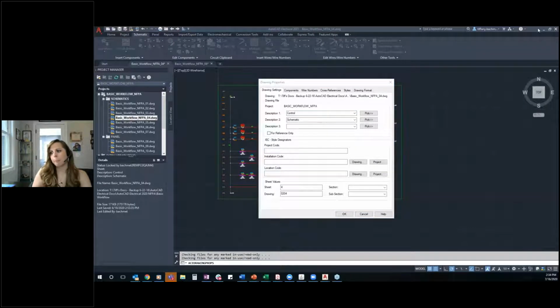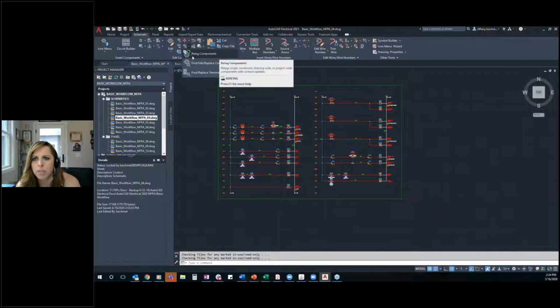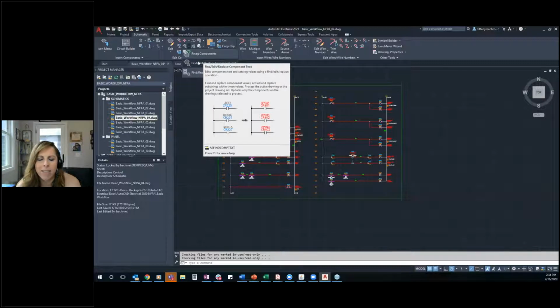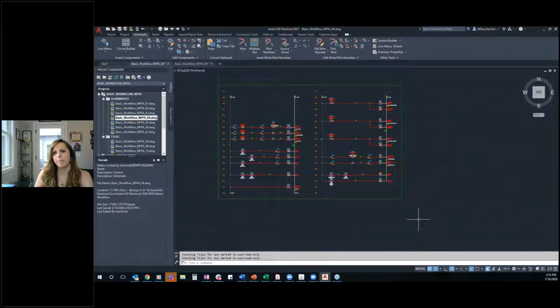And then Tiffany, I think you use the Find, Edit, Replace tool on the project tab. Ron is asking where that's located. Great question. It's on the schematic tab of your panel, kind of right smack dab in the middle of Edit Components. Under the top category that you're typically always going to see, Retag, it's underneath here called Find, Edit, Replace. It's a little gem that's a bit hidden, but absolutely one of my favorite commands for some really great productivity enhancement for project-wide updating.